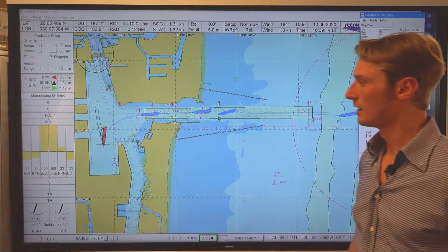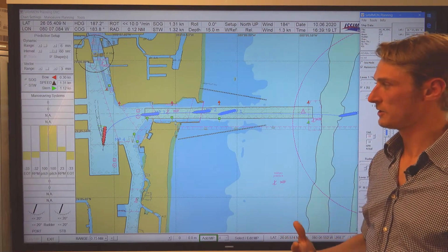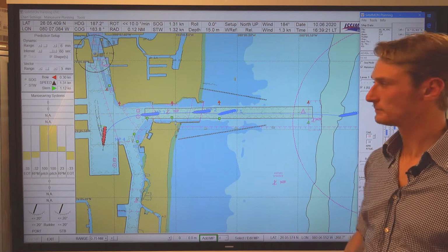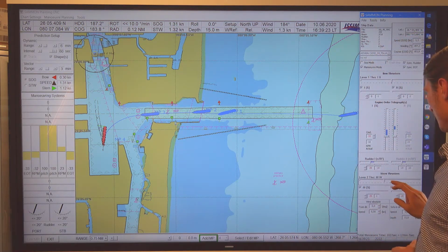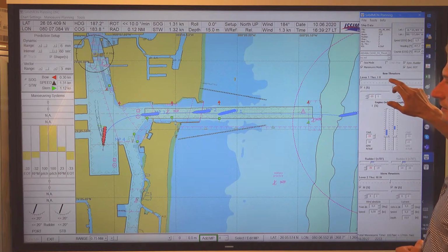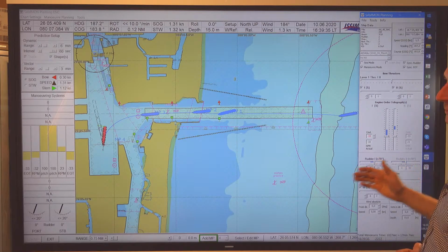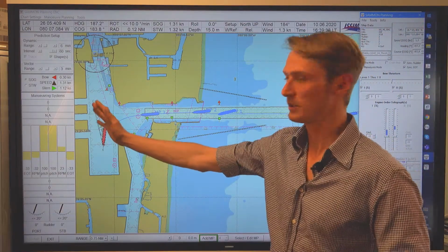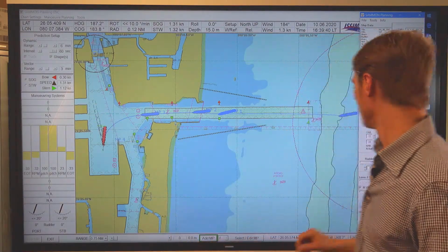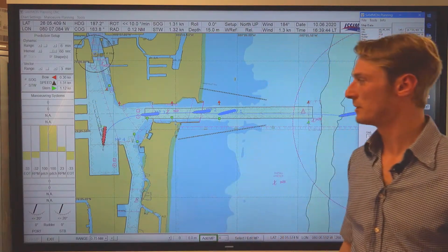Now, as I'm sailing astern, of course, it's very helpful and easy to steer with the stern thruster. And as I'm moving astern, there's no need of having the rudder put 20 degrees to port side. I set it to 0 and had almost no effect. And now I'm able to steer towards the pier.